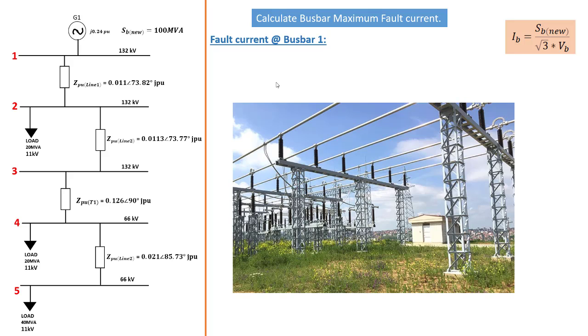In this tutorial, we're going to focus on how to calculate the potential fault current that might flow on this bus bar in case of a short circuit. That is the main reason that we calculated the per unit values, because precisely they're going to help us determine the magnitude of the fault current. When we talk about the prospective fault current, it is the magnitude of the fault current that might flow at any point in a circuit in case of a short circuit.